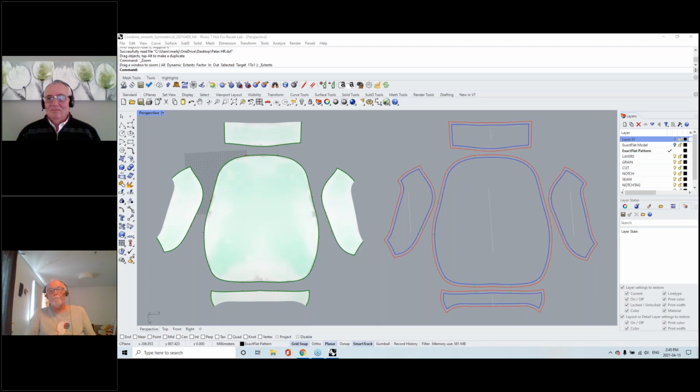Thank you, Peter. I think this will be for Mark or even Peter. How can we create our own material with a specific strength each side in Rhino or ExactFlat, please? That's a question for Mark. Okay, so how can we create our own material with a specific strength each side in Rhino, or EF, I suppose is ExactFlat. All they need is the parameters of the textile. So if you're a textile inventor, you have to test your own textile and tell ExactFlat what its moduli are in bidirectional moduli, and it uses that information and only that information for the flattening process. Is that right, Mark? Yeah.